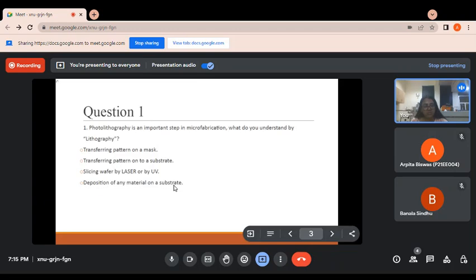Then on the deposited material we want to transfer a structure, like if you want to deposit an IDE pattern or a micro heater. So we follow lithography, and by this lithography process whatever pattern we want to transfer is transferred from the mask to the deposited material.